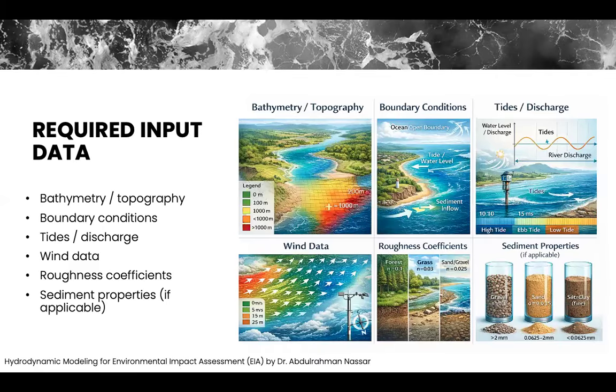So what is the data required for hydrodynamic modeling? First, we should have bathymetry data. We are talking about a water body, and this area should have depth data. This bathymetry data we can get from a field bathymetry survey, or we can get it online, or we can do both.